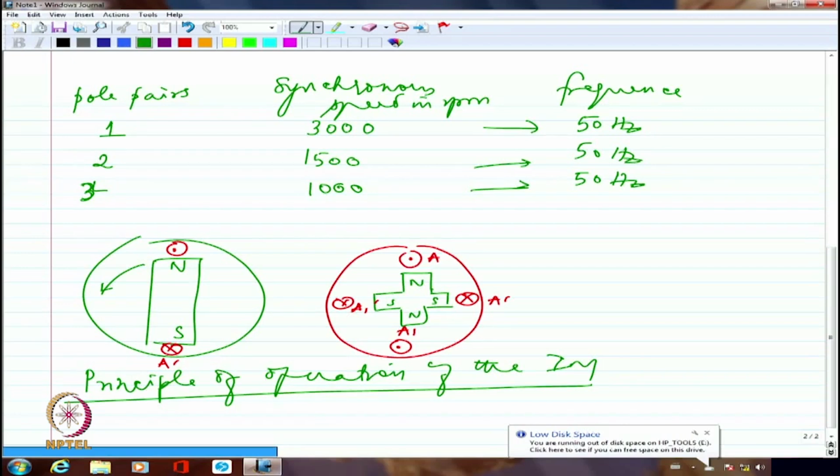If I need to short circuit it, why bring it out? That is a question mark you may have. I might like to modify the characteristics at a later point. So I reserve the rights to modify the characteristics. That's all it means. So unless I short circuit the induction motor's rotor terminals, the induction motor will not start rotating.